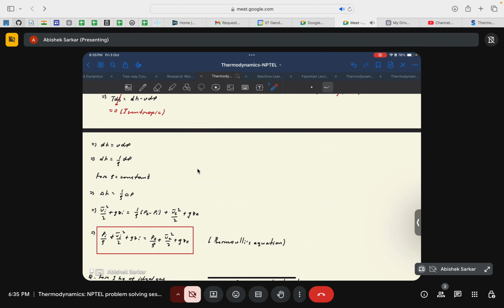Okay, and the reversible perspective in fluid mechanics can be considered through the fact that this kind of equation is usually treated for inviscid flow, where the viscosity is not considered. And in the perspective of fluid mechanics, the internal irreversibilities that can be generated because of the flow through this duct are because of the viscosity.